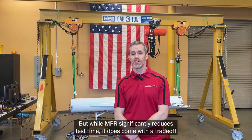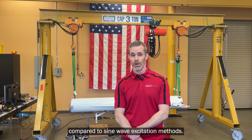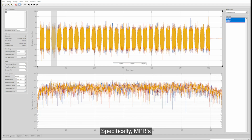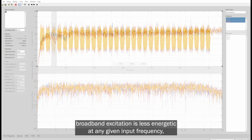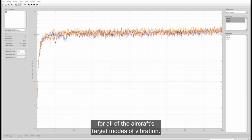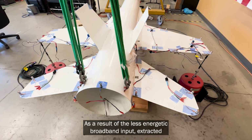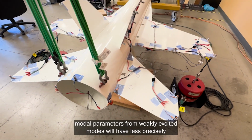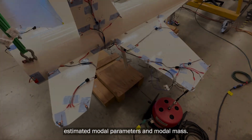But while MPR significantly reduces test time, it does come with a trade-off compared to sine wave excitation methods. Specifically, MPR's broadband excitation is less energetic at any given input frequency, which of course includes the frequencies for all of the aircraft's target modes of vibration. As a result of the less energetic broadband input, extracted modal parameters from weakly excited modes will have less precisely estimated modal parameters and modal mass.